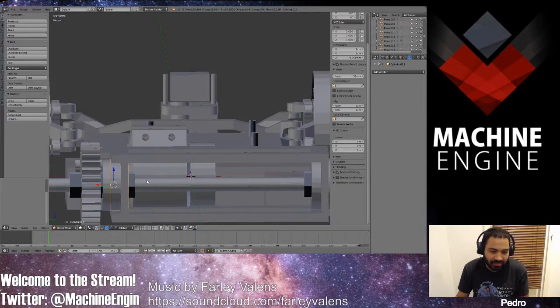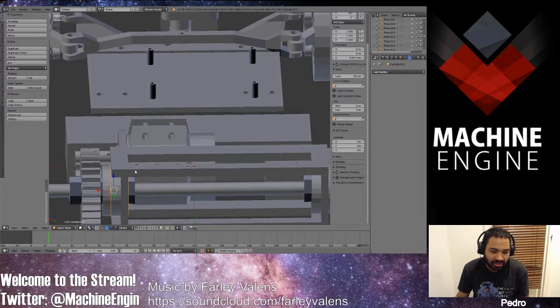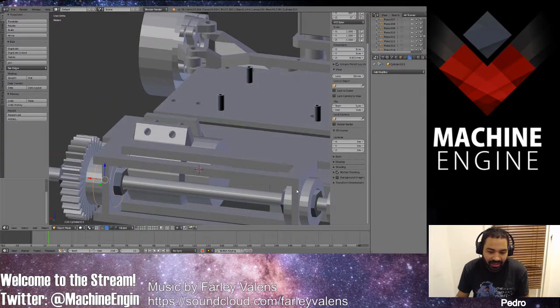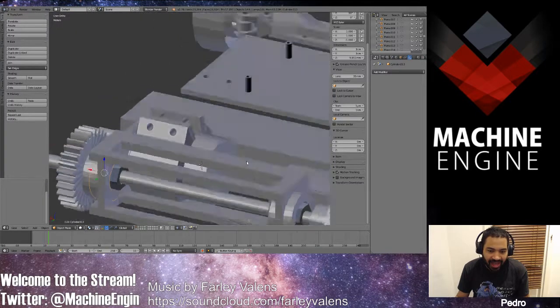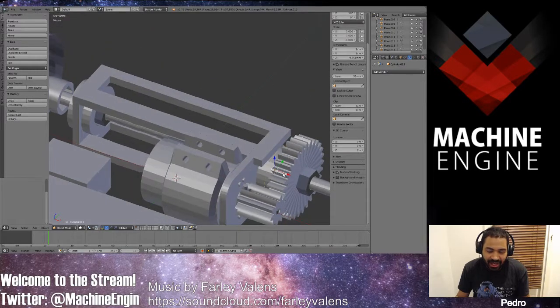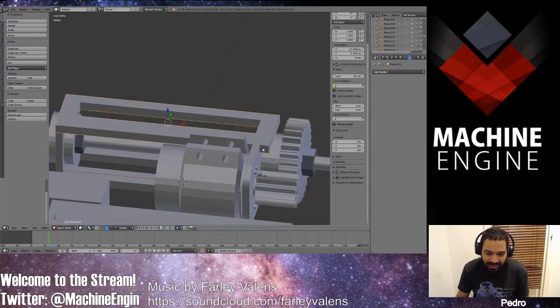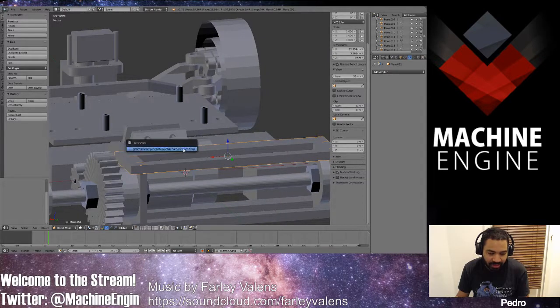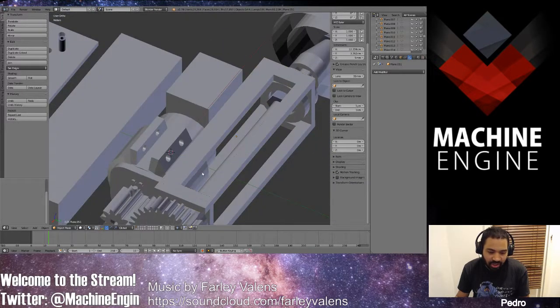This side is going to be flush, because if I print on this side, it's going to have overhanging here, so it's going to print all this material to support it, and it's not going to work. But on this side we won't have that problem. You see here, it is doing that, but I'll need minimal material to get it printed properly, so it's okay.